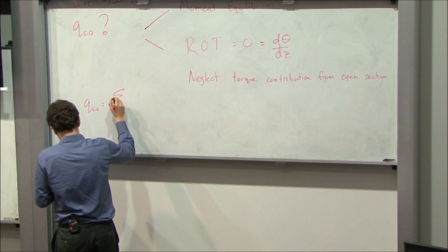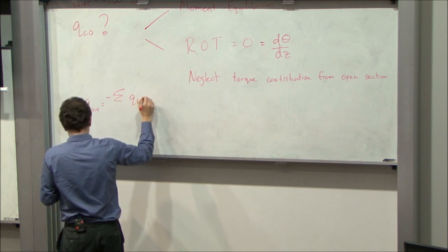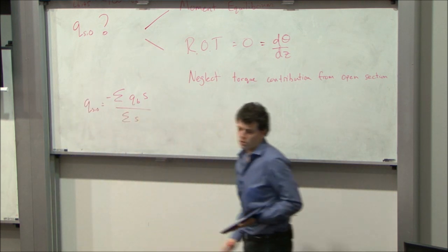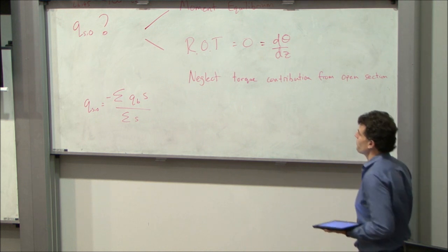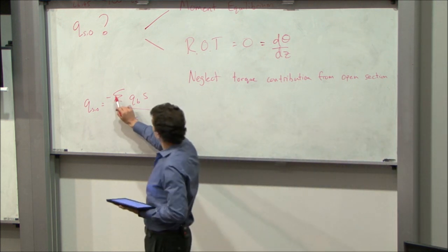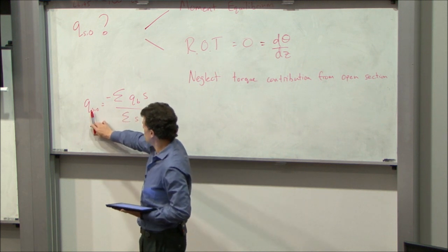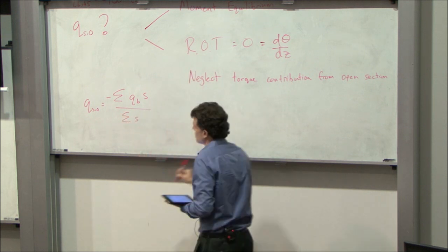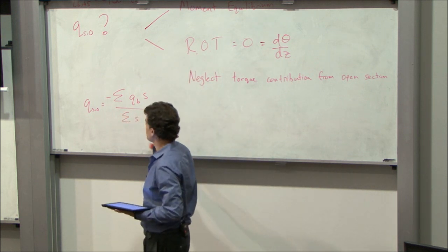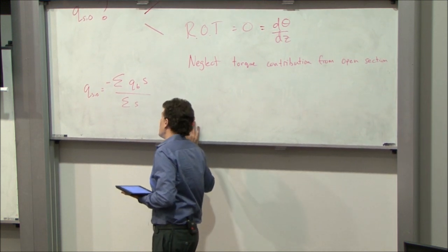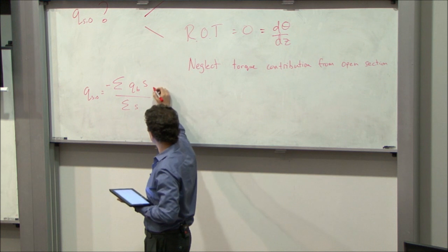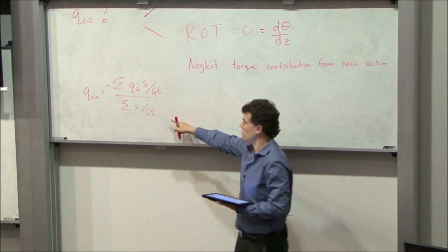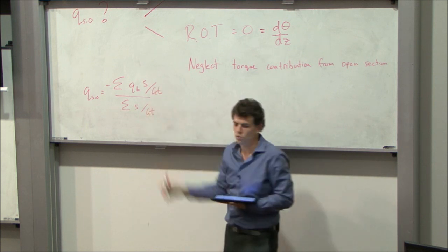Therefore, the form of the QS0 calculation that is most applicable to us is this one, where as long as we're doing these in the same direction, QS0 and QB in the same anti-clockwise direction, then the sum of QBS over the sum of S will give us QS0. Now, in the general version of this formula, there's GTs and other things that hang around, but we're assuming all of that's constant for this problem. So all the other terms drop out of the equation.